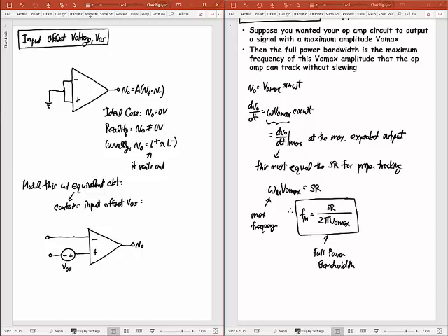Okay? And you'll measure this in the lab. You'll figure out how to determine this offset voltage by basically determining the voltage that actually makes the output equal to 0, but you should be doing that in the lab. But typically, the value of VOS is going to be on the order of 1 millivolt to 5 millivolts. Okay, in bipolar technology and MOS, it could be worse actually. So it depends on what kind of op amp you're using.